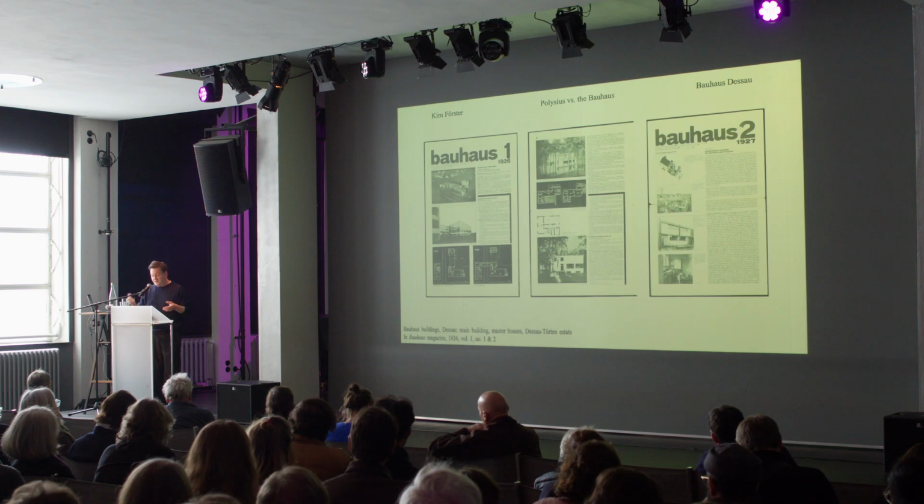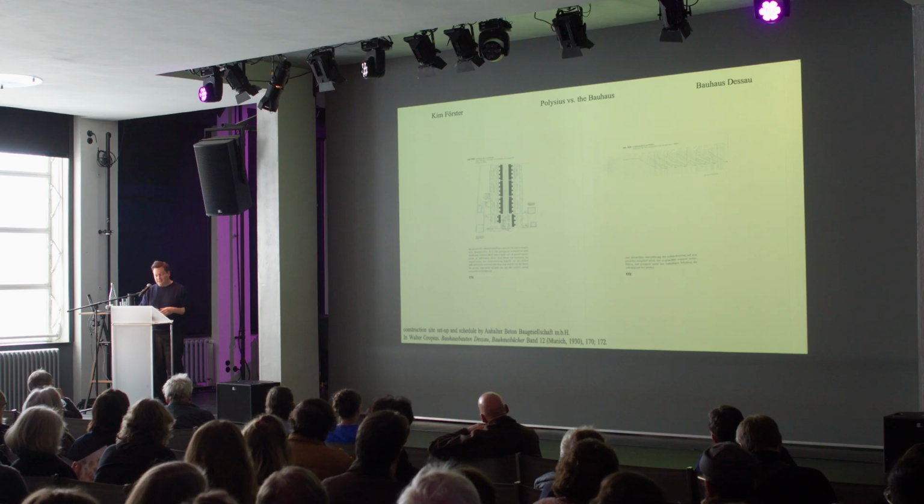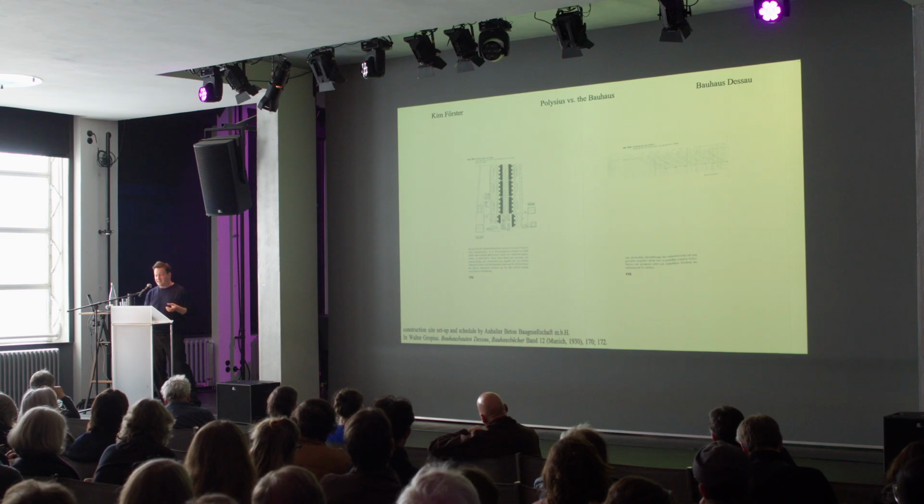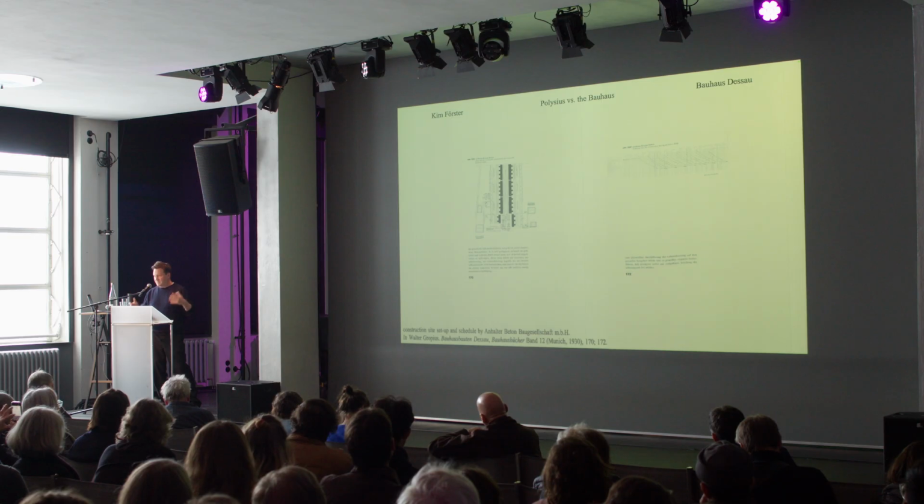The contractor for Dessau-Törten, Anhalter Betonbaugesellschaft, a civil engineering and concrete products company, also from Dessau-Zerbst, otherwise involved in industrial construction of factory buildings, was drawing up a meticulously planned construction site setup and schedule plans. Accordingly, concrete was mixed on site with local sand and gravel, but shipped cement was transported to the prefabrication and construction sites. And cranes here moved on rails across the site, reshuffling prefab concrete elements, enabling an enormous acceleration of serial production, as documented then in promotional films.